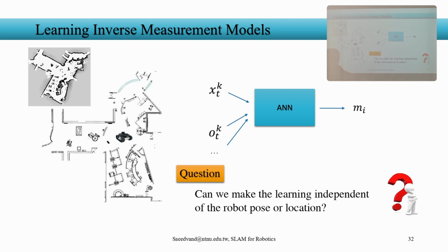But what it can give you is scanning the surrounding obstacles and environment, and learning that my sensor scan says the obstacle is here. Is it really there? It scans and says which of them are really there, and actually learns the error model of the environment. Then the output is a local map instead of a global map, and says, okay, wherever the robot is, it can more accurately give you the map of that part only.